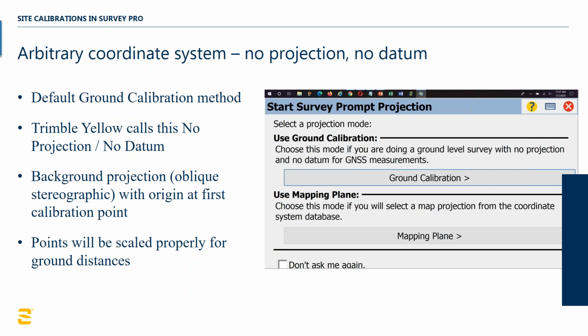The moment you use the adjust menu and you take something that was observed and scale it or translate it or rotate it manually with the adjust menu, we have to sever the connection to the original observation, and we turn that thing into a regular stored point that is no longer connected to observation.